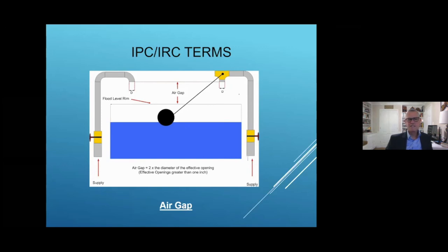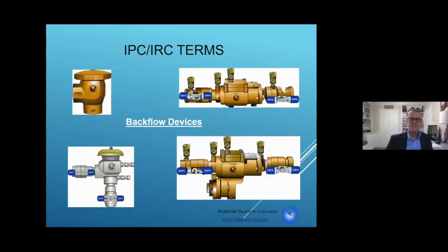And then the water supply is coming in on the left and on the right, and you can see that there's vertical free atmosphere from the discharge point of those supply pipes to the top of the supply area, the area that's accepting the water. So there's no way to mess that up. You don't risk contaminants jumping out of the vat or the storage tank up into the pipe. And an air gap works very effectively towards elimination of contamination.